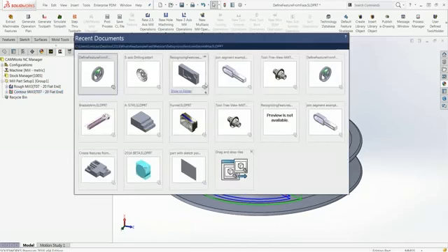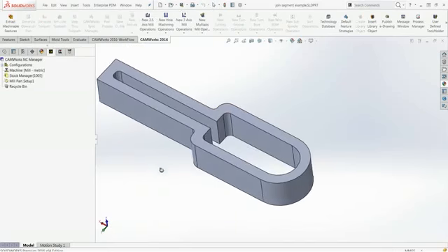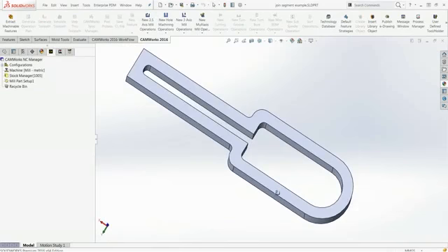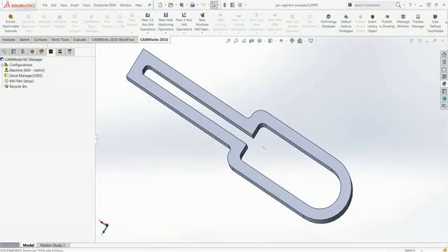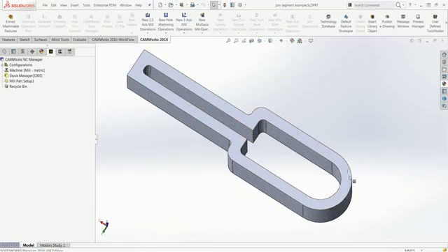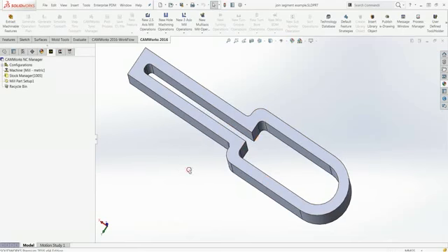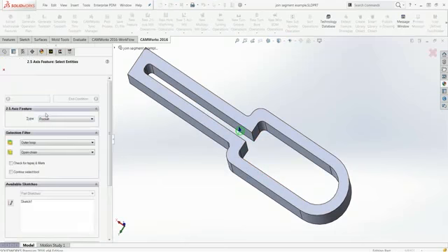And another one that I will show you is on this part. It's just kind of easier to see. So if I wanted to just machine this section at the top here, and I wanted to use maybe a really small tool to get this little part here, in previous versions I wouldn't be able to select this whole thing because it actually stops here. And it has a little gap in there. I would actually have to create a sketch to select that area. So now in 2016, you can go ahead and select all of these features. And again, I'm setting on open chain.